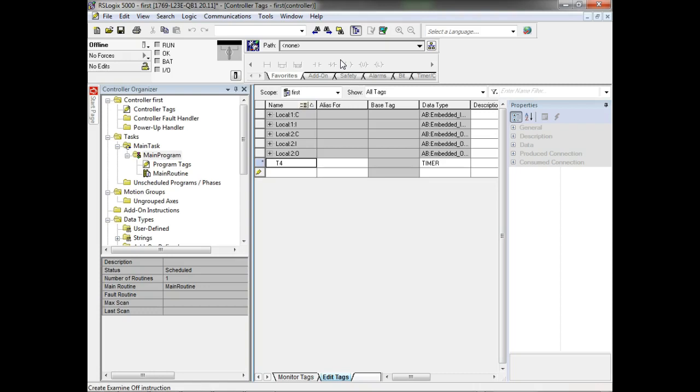So if you're using a modular PLC, you have to go out and specify which one you're using. The PLC that we're using, the LE23, automatically has a 16-bit input and a 16-bit output. It puts the input at word 1, and it puts the output at word 2.